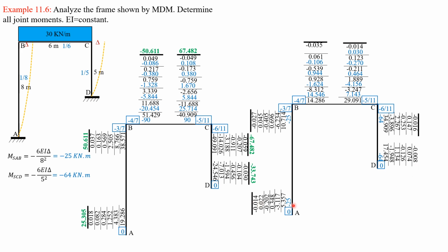Then we add the moments at A, MAB, second phase, negative 22.606, MBA, negative 20.211, MBC, 20.211. So the calculation is correct. And that's 0.062, by the way. Then adding this column, we have 30.842. Adding these values here, we have negative 30.842. They are equal. So that means the calculations, tabulations are made correct.